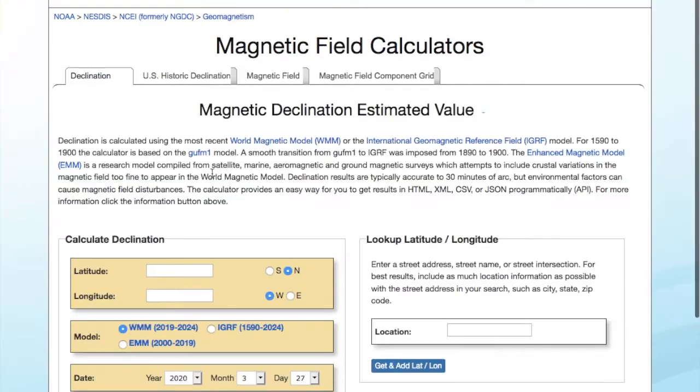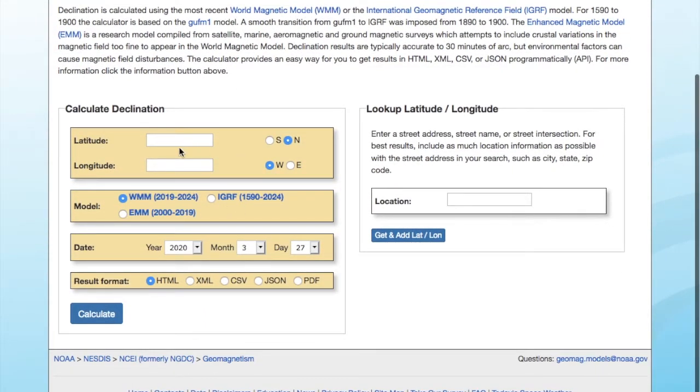And then it gives you these boxes here. So latitude always comes first, and then longitude. These were the values in the bottom right corner that we recorded previously on Google Earth Pro. The coordinates that they give you on Google Earth Pro are in the DMS system, so they're given in degrees, minutes and seconds, and the seconds are to 2 decimal places. Later on we're going to convert this to the decimal degrees system.